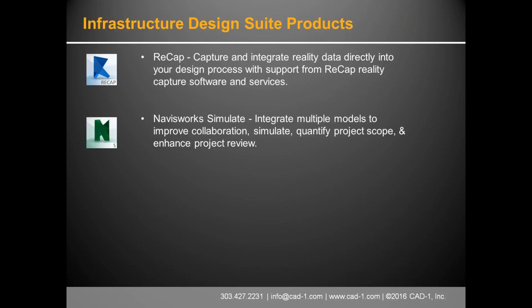On the civil side, Brian, what do you think maybe a good example of someone might have various road projects or other applications where someone might use this, other than owners and things? I could see how an owner, but maybe throughout the workflow. I've seen it, Navisworks honestly is used primarily by contractors in the civil industry. I've seen heavy civil contractors create Navisworks models that actually show the timelining of the project being built. So phase 1, we're going to demo this area. Phase 2, we're going to build up this area, and then we're going to go demo that area. And you can timeline this and actually simulate the whole process going through.